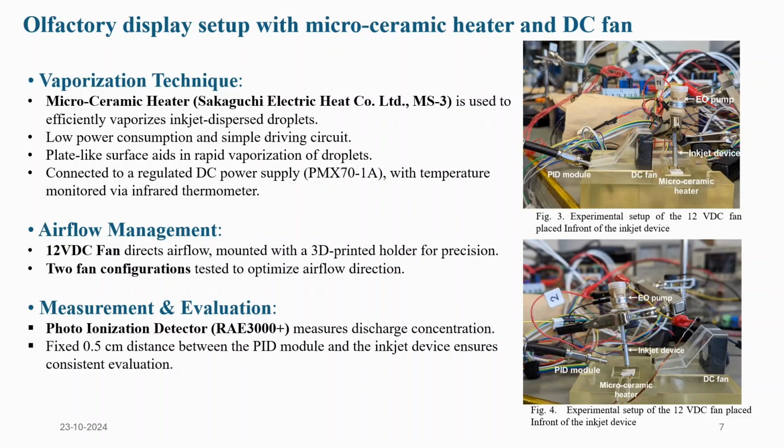For airflow management, we used a 12-volt DC fan with a 3D printed holder, which drives the airflow through a proper channel. For measurement and evaluation, we used a PID module, RA3000 plus, and the distance between the PID module and the point of dispersion was set to around 0.5 centimeter.